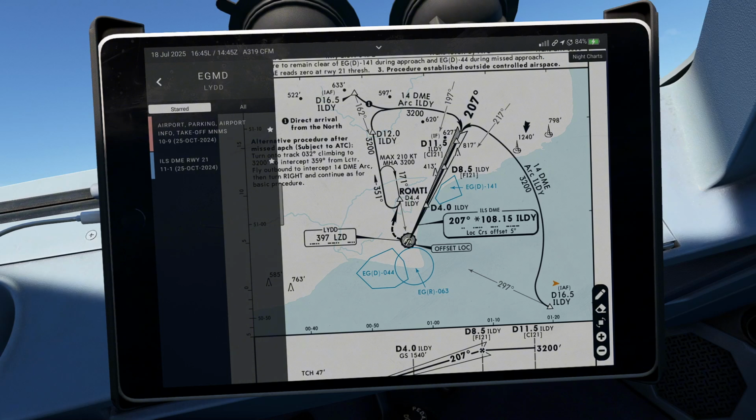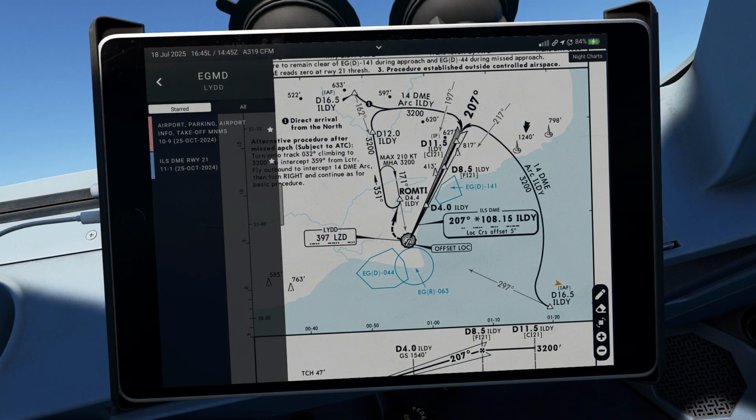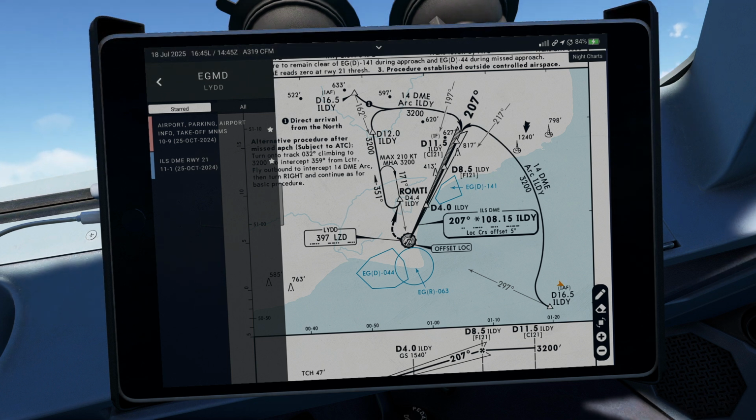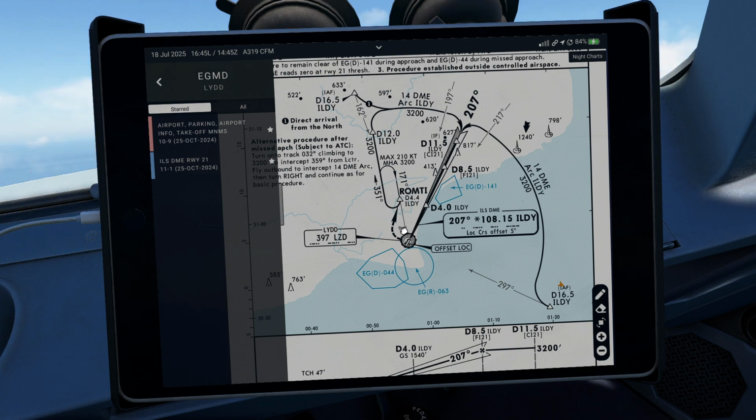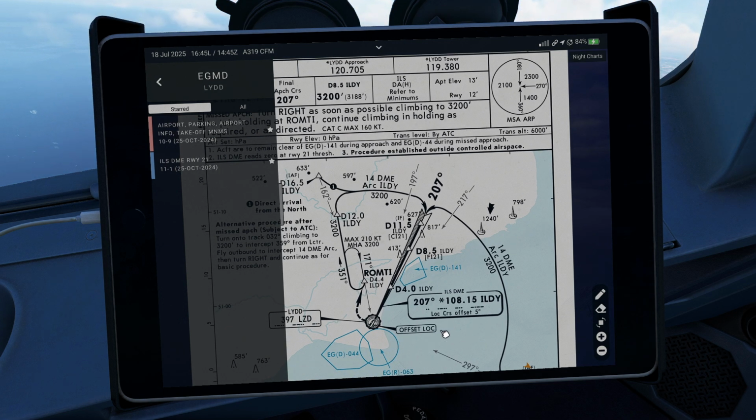As you remember, at the beginning and also in the introduction of the offset ILS approach, I mentioned that if you want to design 3-dimension or 3D approaches within offset criteria, you should observe the 3 degrees or less offset angle between the localizer and the extended runway centerline.